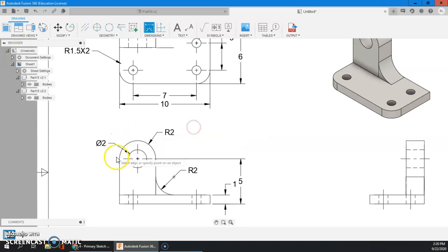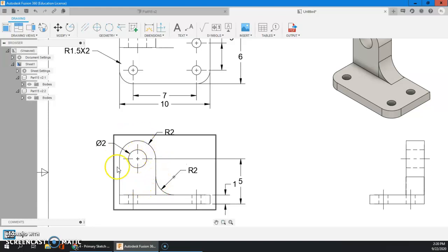And if I take the radius of this, it tells me that this is 4 inches wide right here. So I can find out how big this piece is, and the center mark tells me where the center of it is, so I can locate that as well, because this arc and this circle share a common center.